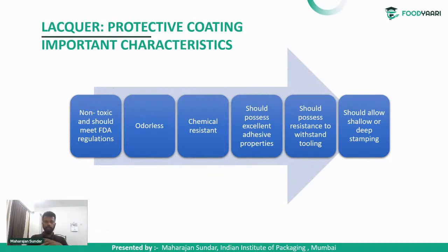This lacquer coating should be non-toxic, and it should meet FDA regulation. It should not give unwanted odor. It should give chemical resistance. It should possess excellent adhesive properties with the metal container, and it should possess resistance to withstand tooling. For example, after opening it, we just take a rasamalai or gulab jamun using a spoon. If we are taking 10 pieces by scratching the inner part of the container, the lacquer should not get removed, so it should withstand tooling, and should allow deep drawing or stamping.